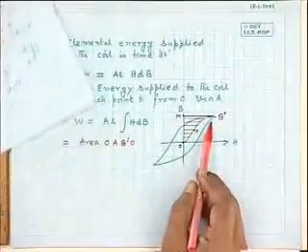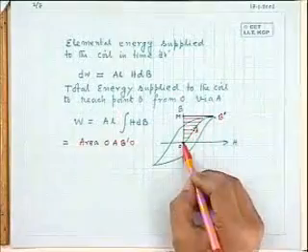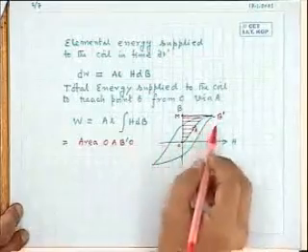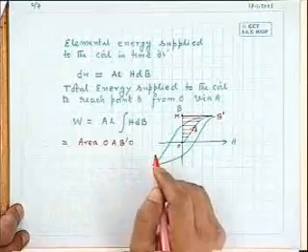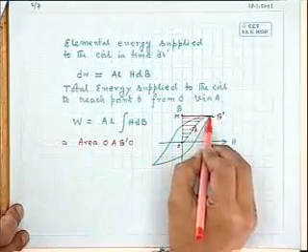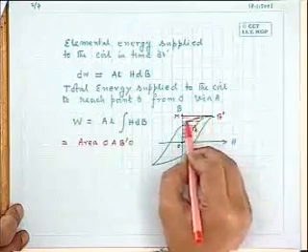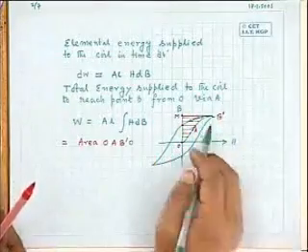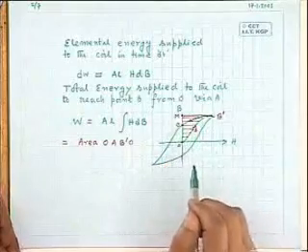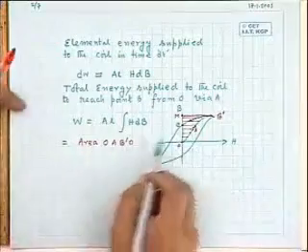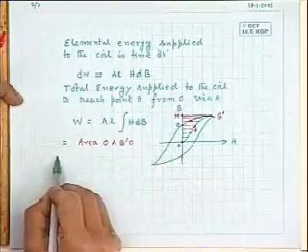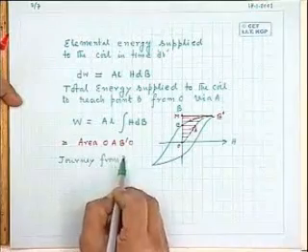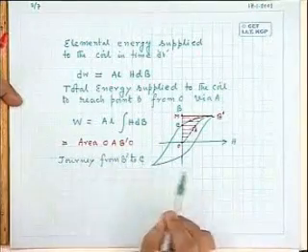Now suppose after this the current is being decreased, so the point moves here, and the energy received is given by this area. Now the current decreases because of the sinusoidal nature of current. The point of operation will now follow this path. That is, from B dash it will come to C. So in its journey from B dash to C.